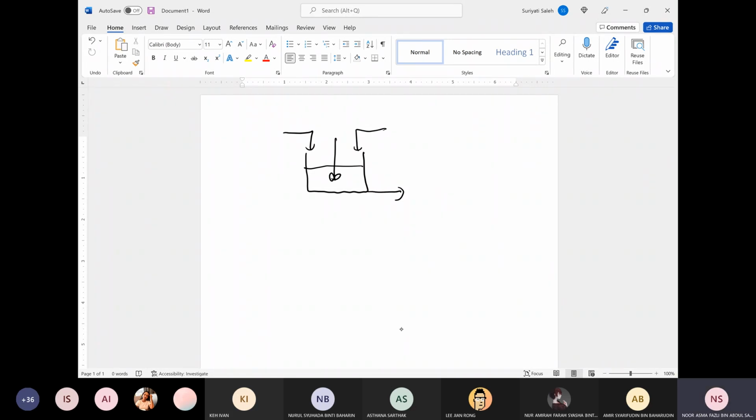So when you have one unit operation, the scope is narrow. You just want to make sure the level will not exceed the capacity or will not violate the minimum capacity. So in this case, only level control is necessary. Flow control is not needed.